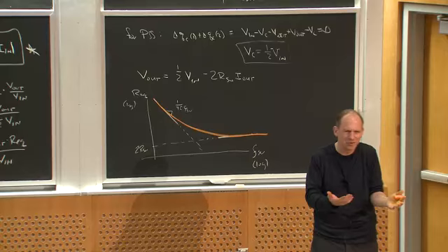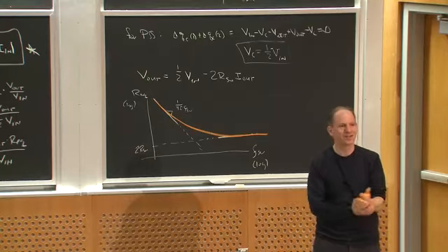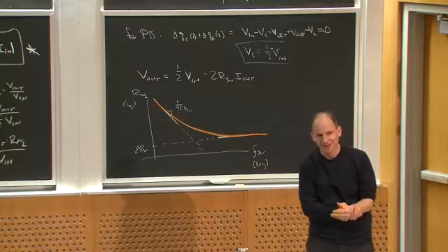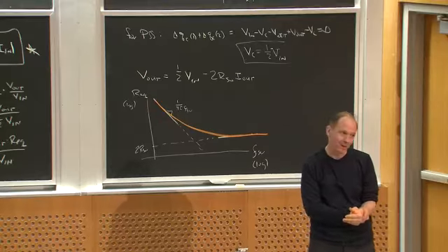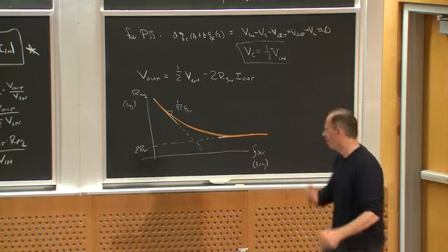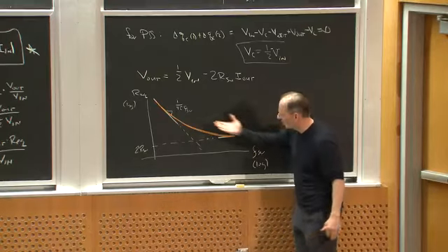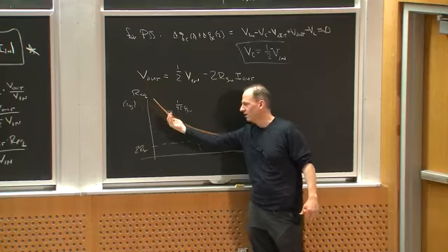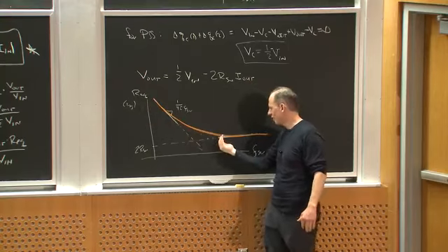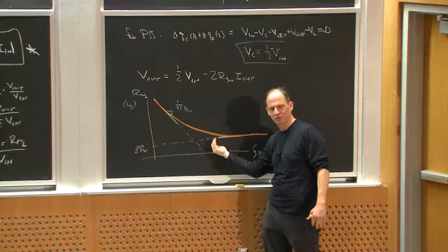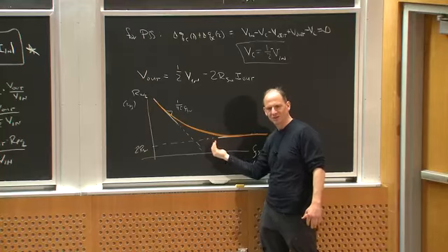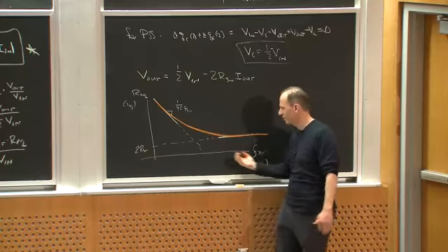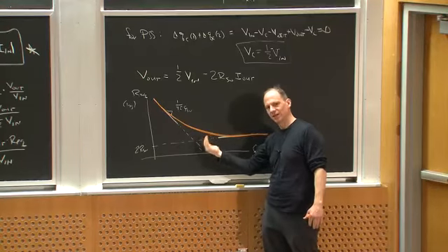Well, if I'm charging through 2 switches all the time, I have to eat the on-state loss of those switches, right? I can't have 100% efficiency. But if I'm using 10 milliohm switches, maybe that's pretty low, right? So essentially what I would tend to do is keep turning up the switching frequency until I get down into this regime where turning it up any more doesn't reduce my output resistance. Because at that point, there are other losses like gate drive losses which get worse with frequency. So I ought to just go high enough that I can get to very high efficiencies.